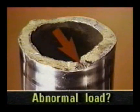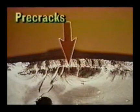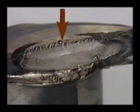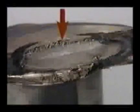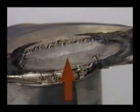Before deciding if failure is due to a material problem, we should verify that loading was not excessive, because excessive loads can start fractures at normal size inclusions. If surface cracks are created during metal forming, heat treating, or processing, they are called pre-cracks and act as severe stress raisers when the part is loaded. Most pre-cracks are ductile or brittle and can be recognized by their different surface texture. Fatigue cracks with beach marks and ratchet marks may begin at the bottom of the pre-crack.